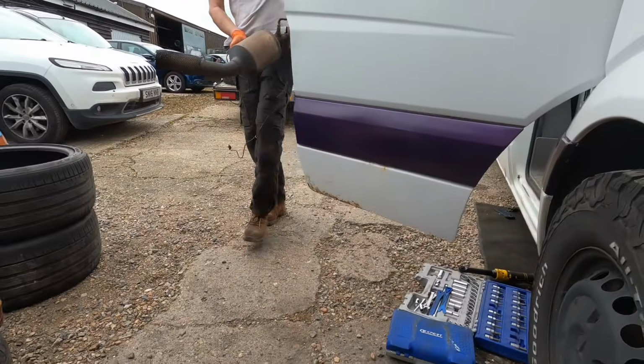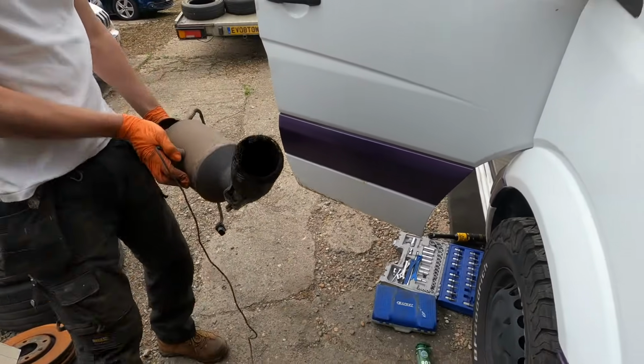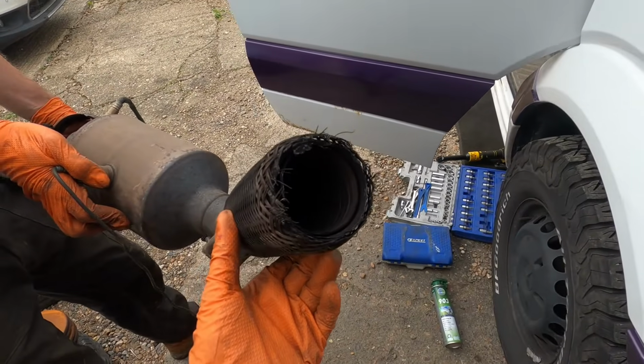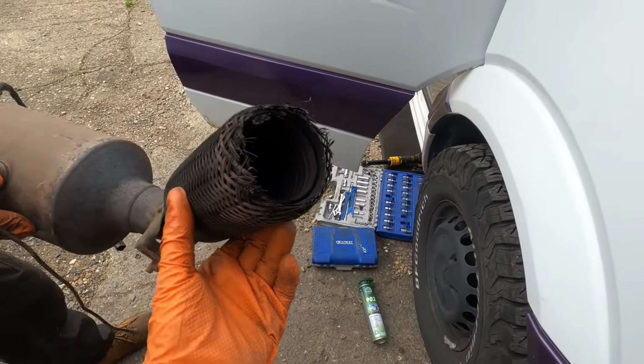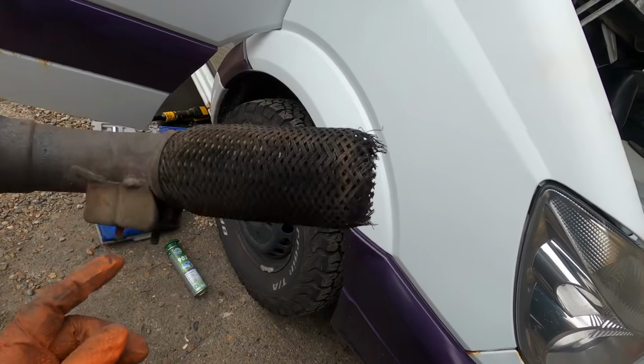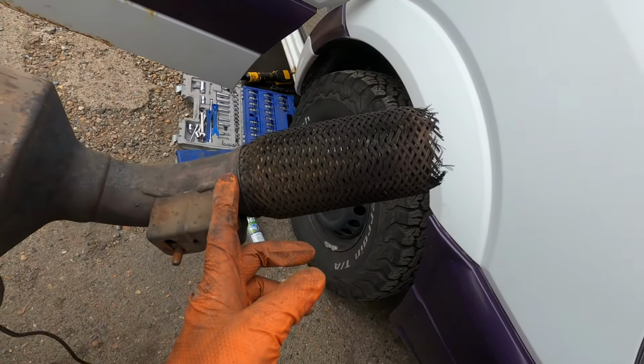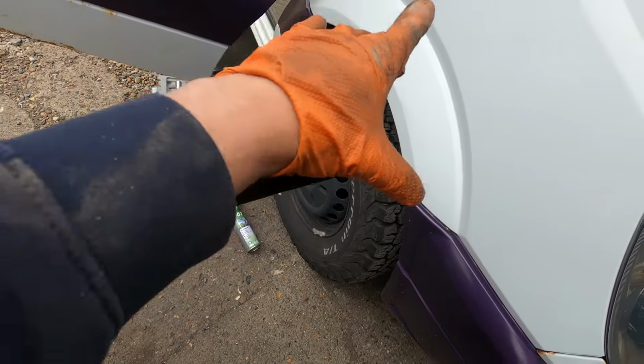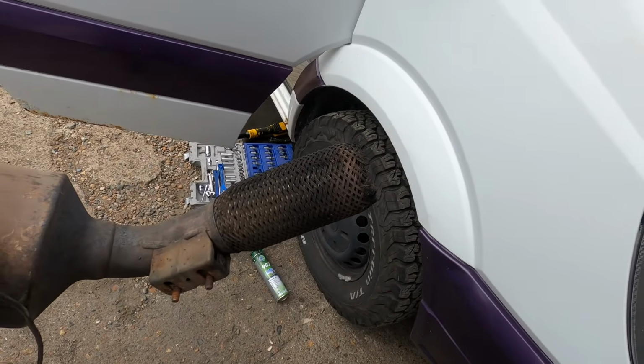Let's have a quick look at this exhaust. See what we were saying. There you go, guys. So that was a reason for the negative pressure in the exhaust system. So the plan is going to be, we are going to have to cut as close to this bracket as possible so we can re-weld this on and then sleeve the new section on that.